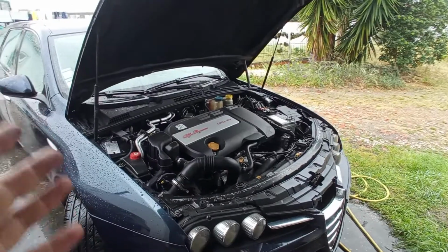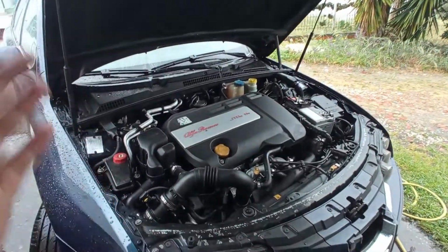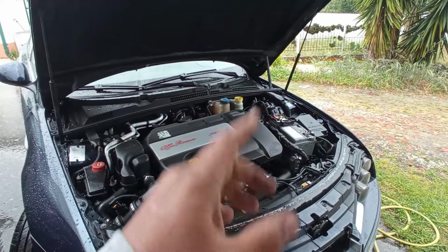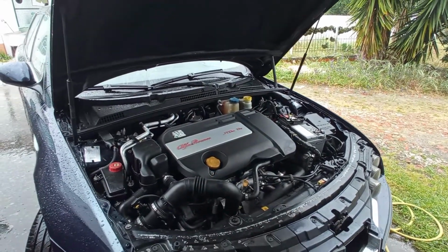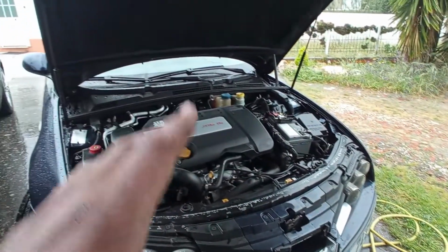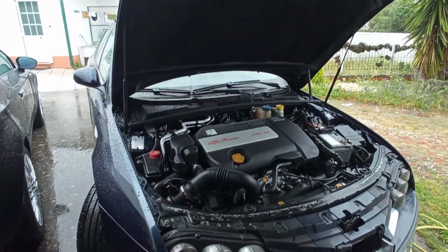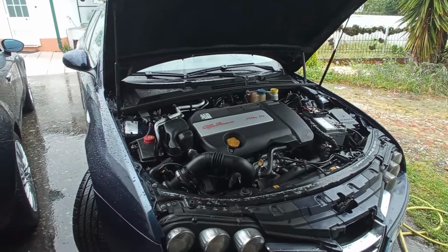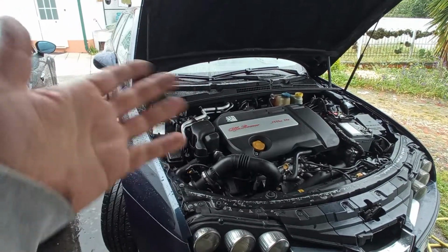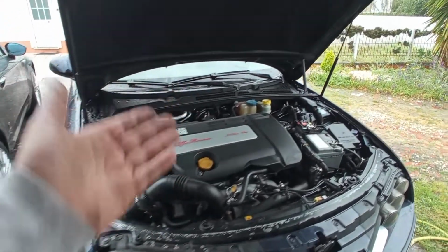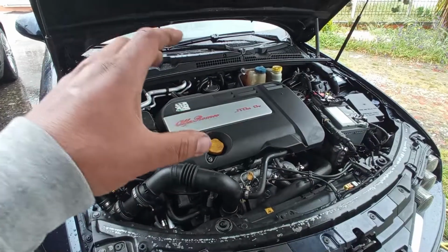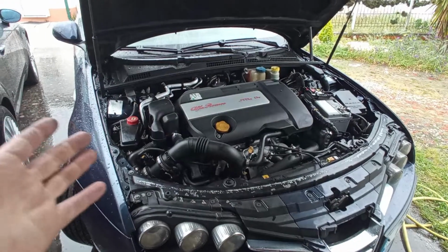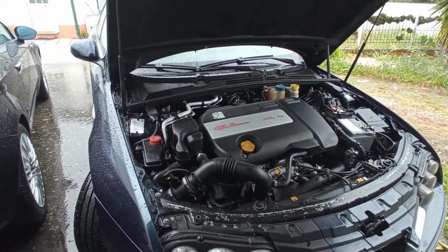So guys, here you have it. The car is back for the remap. Yes, I ordered a new remap, an original map for this car. And indeed, the car had an attempted remap on this. That's why it was so bad. The constant regens and whatnot, it's all gone. So the DPF itself was already deleted in the past. So now we have the original map only with the DPF and the EGR modification. And with that, the car is now back in business.